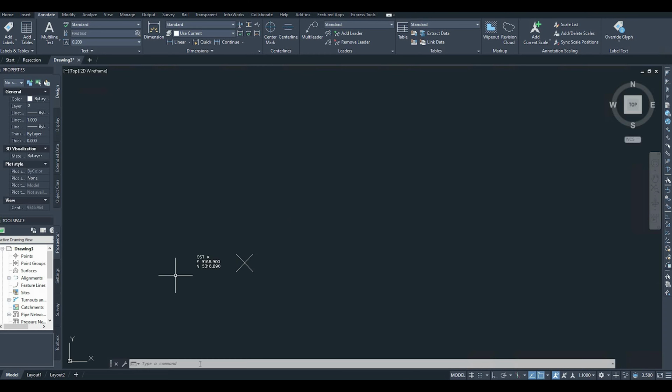Okay, now let's do the same for point B. In the command down, if you miss something, now we will repeat the whole thing for point B. Here I would write down point, and then enter, and then I'm going to provide the coordinates of B, 8901.741, comma, and then 5725.479, and then enter.